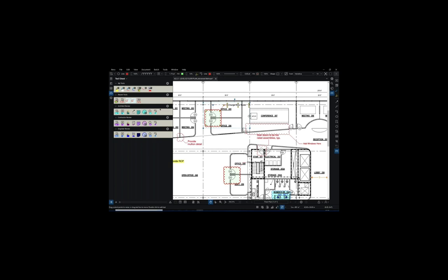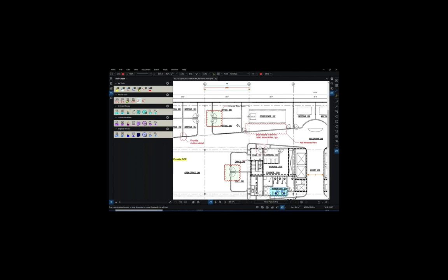Another thing, dimensions are also considered markup tools. Watch this. I had some prefs set already for a dimension tool. You can see the way the tool wants to snap to the content of the PDF. Hold down the Shift key to constrain it horizontally. Click, and there's a dimension, possibly with your own office standards.